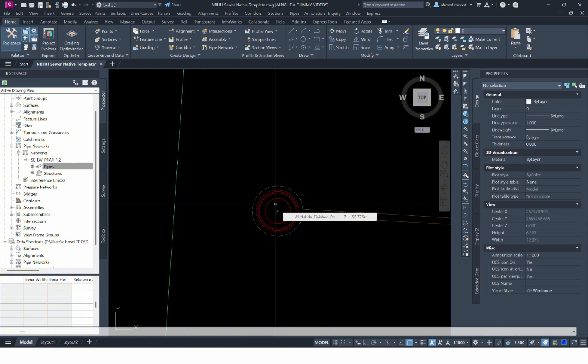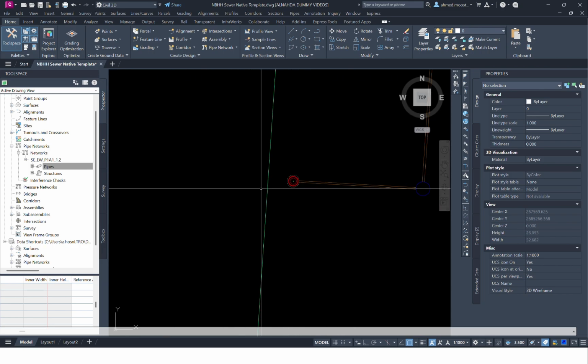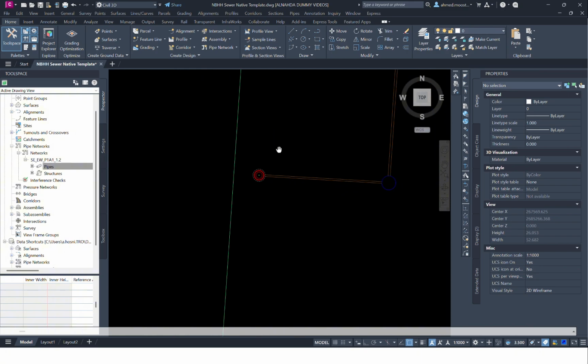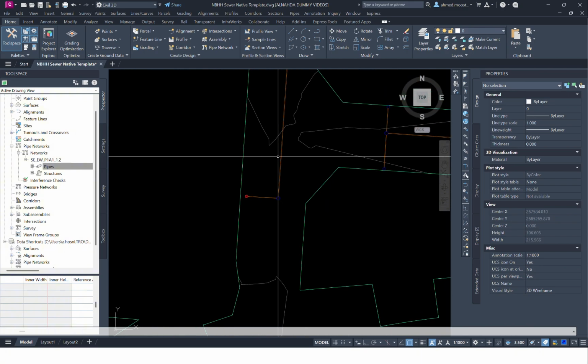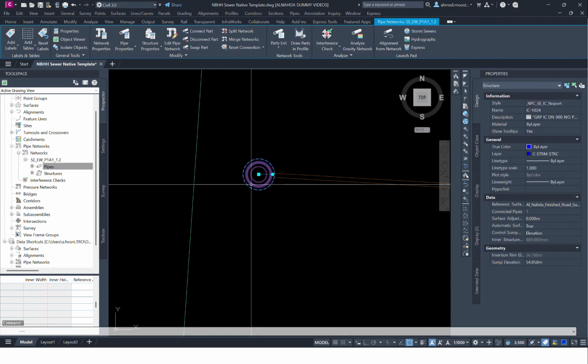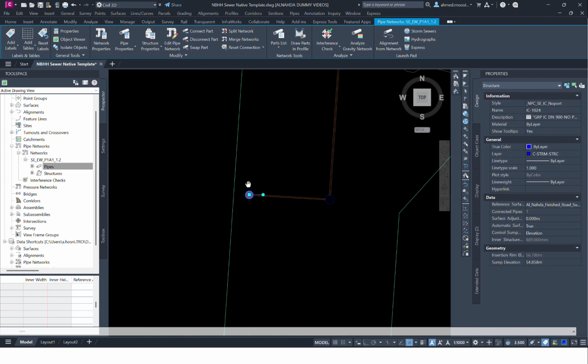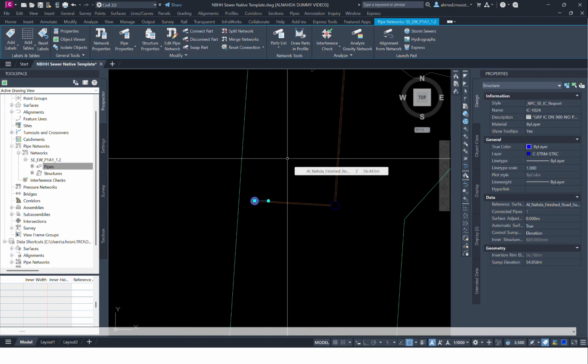Something you need to know also is that the Civil 3D environment shows in 2D. If you have a 2D wireframe environment like the one we have right now, it shows the structure as a block, and this block should be pre-identified before inserting the structure itself, or you can update it from your working folder based on the project.